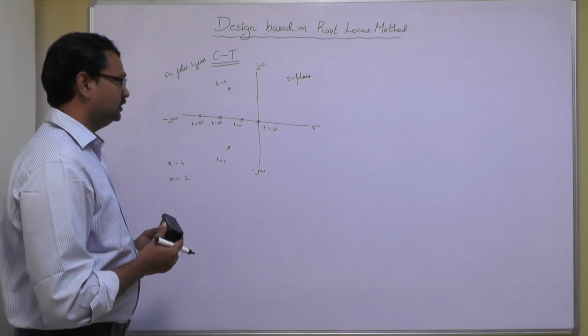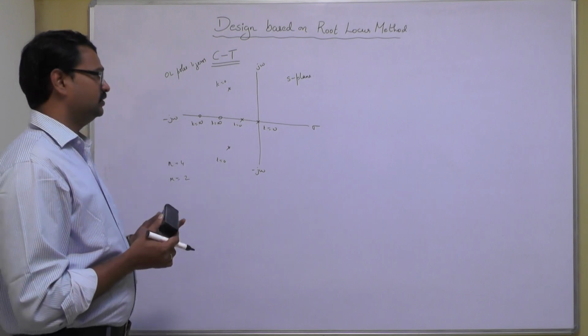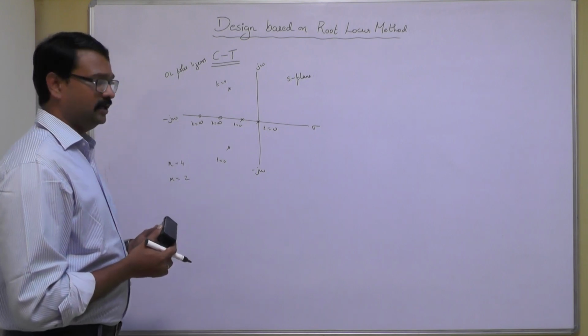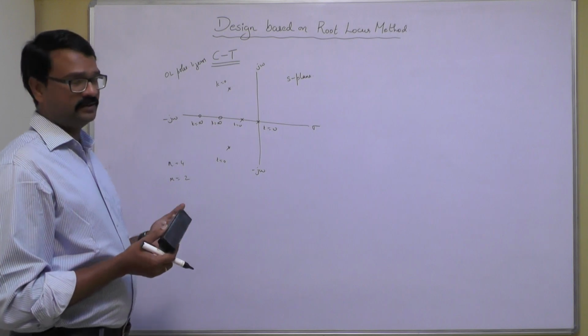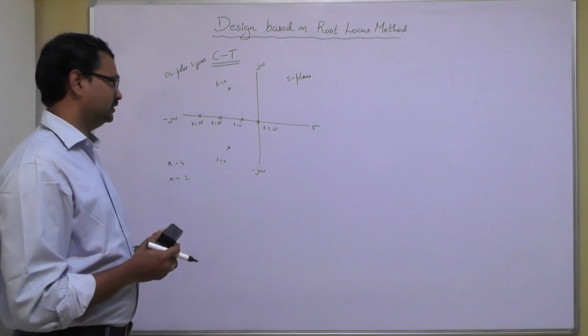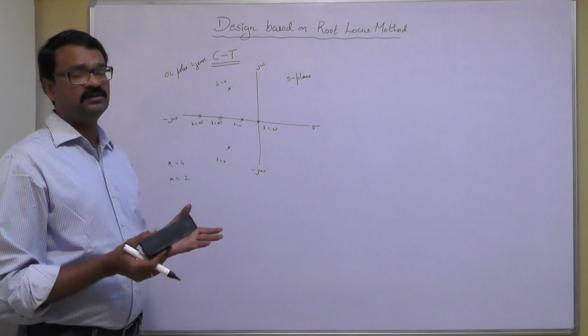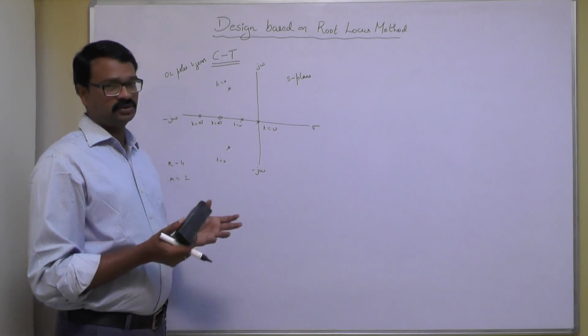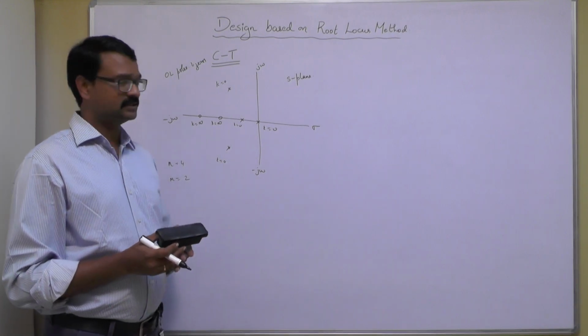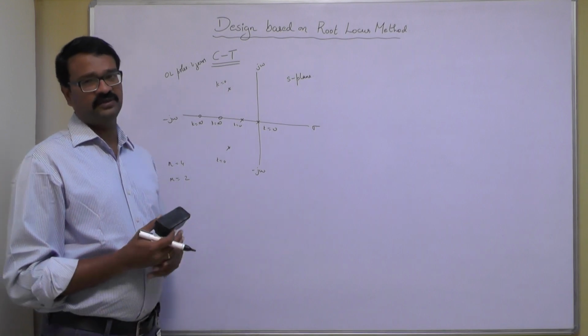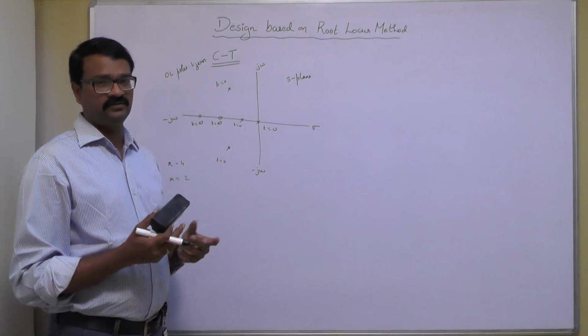The root locus branches start from every pole and end at every zero or at infinity, along straight line asymptotes. The asymptotes start on the real axis and intersect. There may be a different number of asymptotes for any given system.